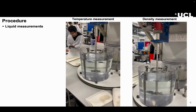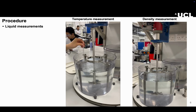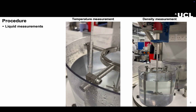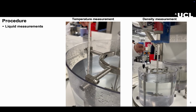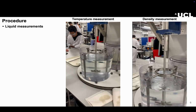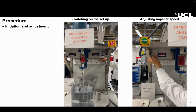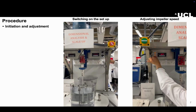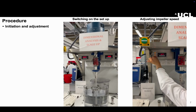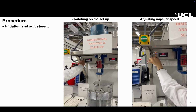The temperature of the liquid is measured using the thermometer, ensuring the reading is accurate by taking it at a suitable point where the bulb does not touch the tank walls, and the value is recorded. The density of the 100% glycerol liquid in the tank is measured using the hydrometer, waiting for it to stabilize before taking and recording the reading. The power switch for the setup is switched on, ensuring that the speed motor and the torque transducers are on and functioning properly. The speed of the impeller is set to a value above 300 rpm, and the torque value displayed is recorded once stabilized.